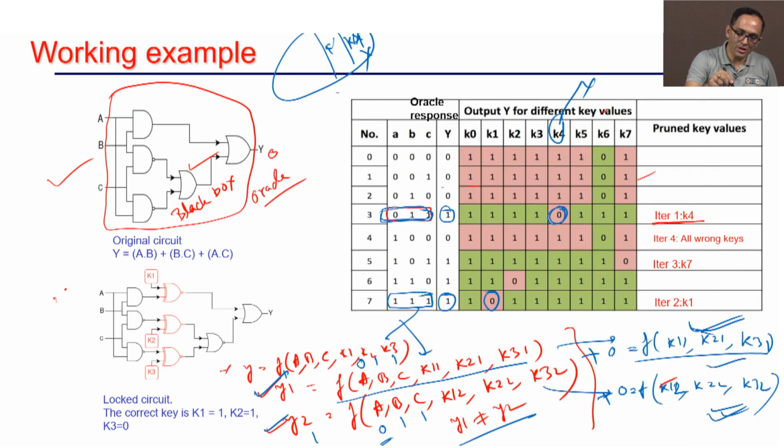Here the way I am doing it is not helping much, because in the search space only the wrong keys for the corresponding input are removed, and there is only one possible wrong key for this, which is okay, right. So this K1 will also be removed. Again I call this equation, this equation, these two equations plus another two equations corresponding to 1 1 1. So my formula size is getting increased. Again I am going to ask for check SAT of that combined formula.